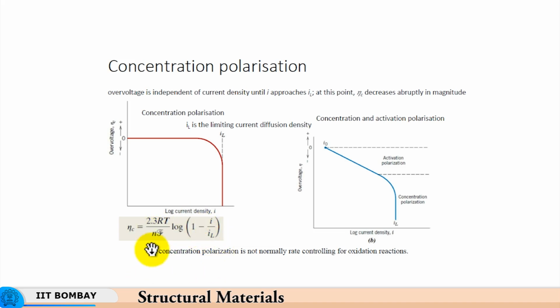Generally speaking, concentration polarization is not the rate controlling process for oxidation reactions. Mostly reduction reactions are the ones where concentration polarization is significant.